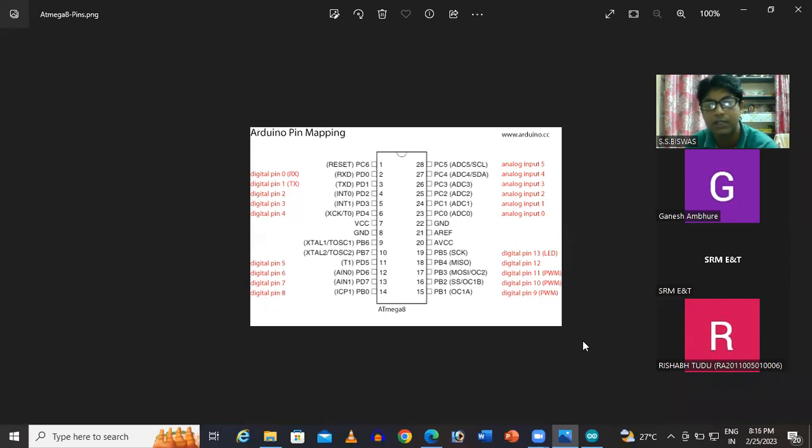So I always suggest to all of my students that whenever you are using any IDE, it's not an issue, but you should do the coding by reading the registers. In PIC controllers, you will be using MPLAB. There are also several libraries there. Rather than going to those libraries, it is better to write bitwise code.